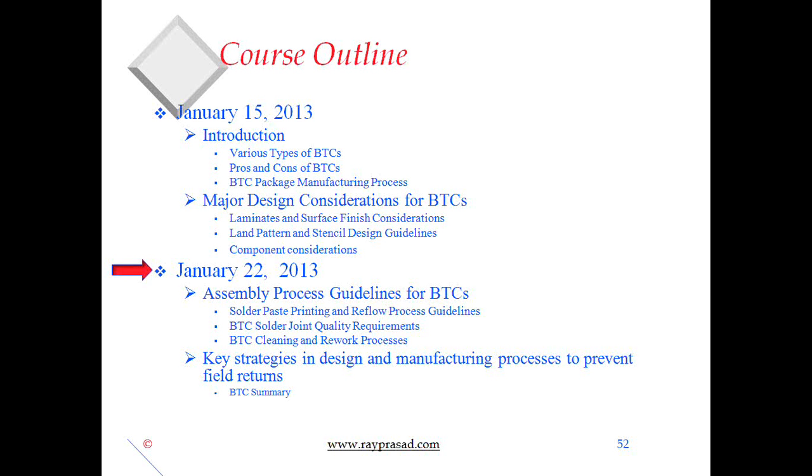Okay, now I understand. It's like a BTC package, but the ball is 40 micron, and it's going on a flexible circuit. So to repeat the question, this is a flex circuit on which you're mounting a flip chip package with 40 micron balls, and by the way, 25 micron is 1 mil, for those of you doing the translation.